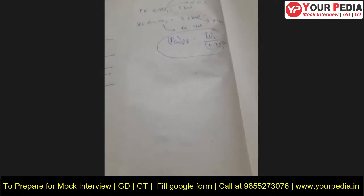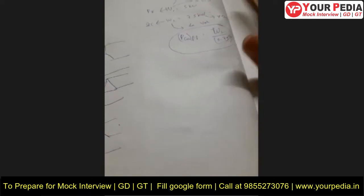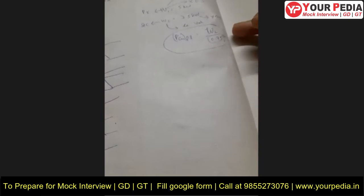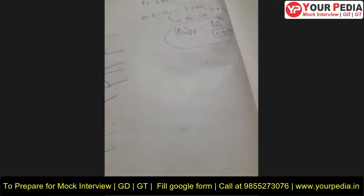What are the applications of a Scott connection? The Scott connection is basically used for conversion of three phase to two phase, sir. In olden days they used two-phase induction machines, sir. And that's why they use the Scott connection for conversion of three-phase to two-phase.